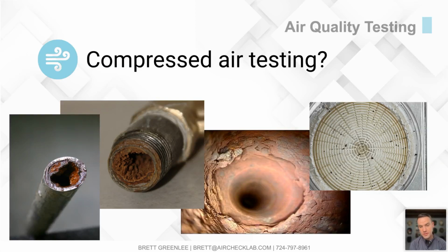Sometimes it can be from our system or from leaks, again, ambient and things like that. But more often than not, the most pointed part of this is what is compressed air testing and how do we validate and verify that our compressed air is free of that contamination, free of those particles, water, oil, microorganisms, potentially gaseous hazards, etc.